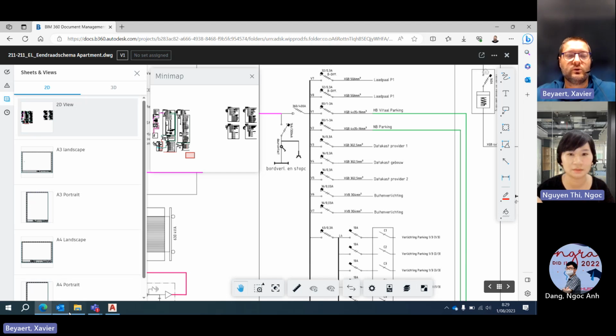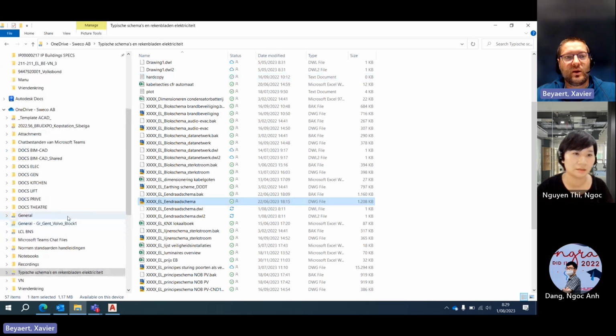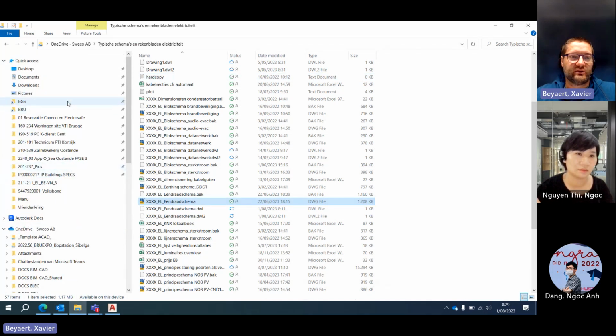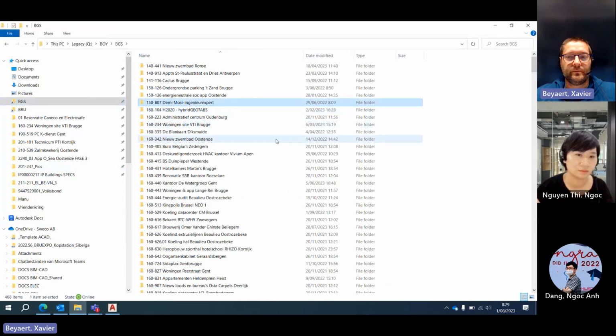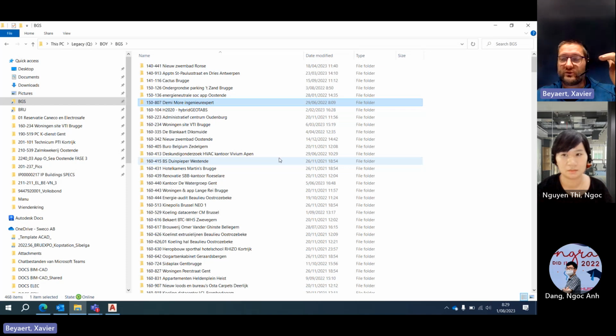On the charging stations we use a simultaneity factor, so we don't say all the charging stations are at maximum load at the same time. So we determine how the power is divided over all the separate charging stations.